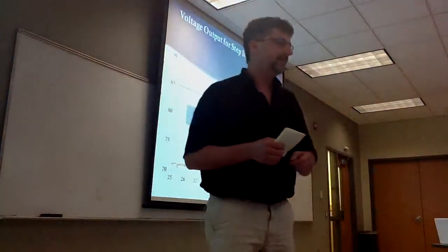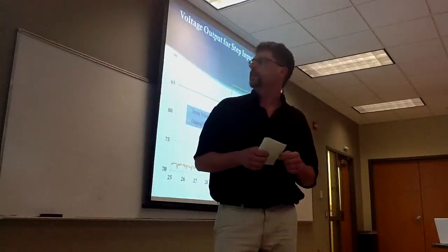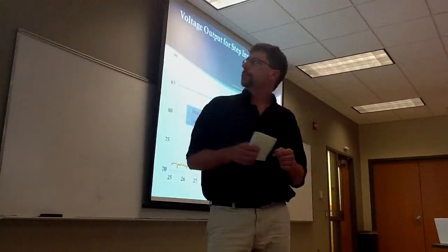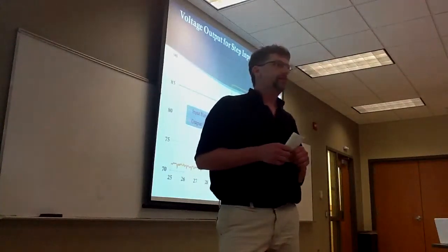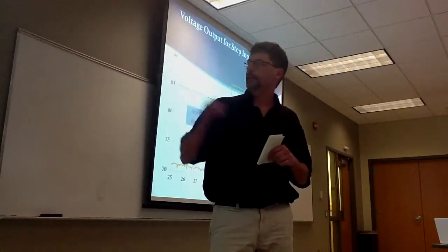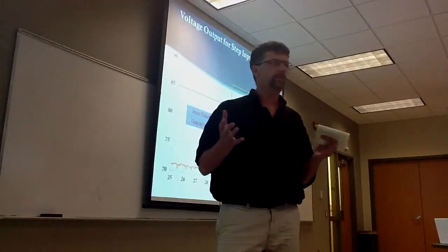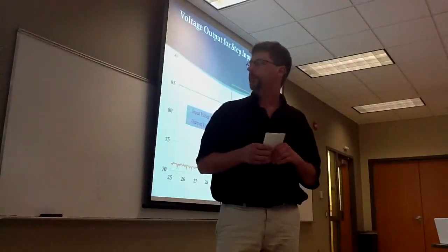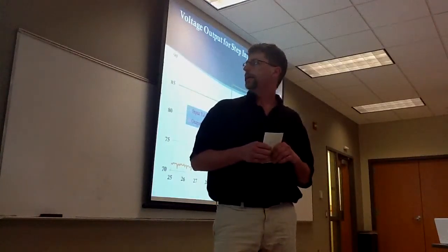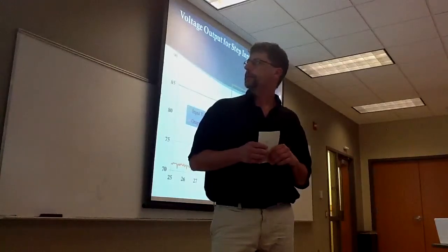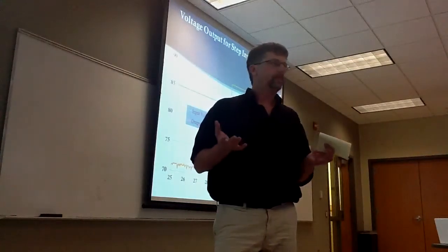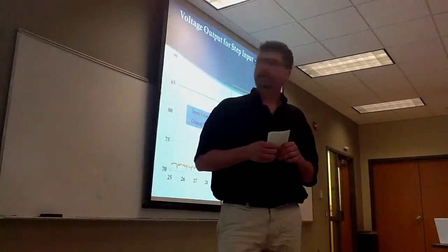Next, we did the step response. In this example is a step from 85 to 90%. It was at 85%, the steady state was around 70.5 volt output. And after the 5% step up, steady state reached was 79.2 volts.